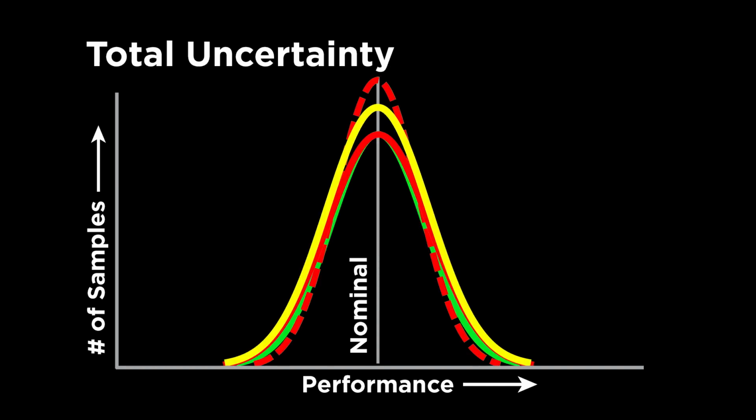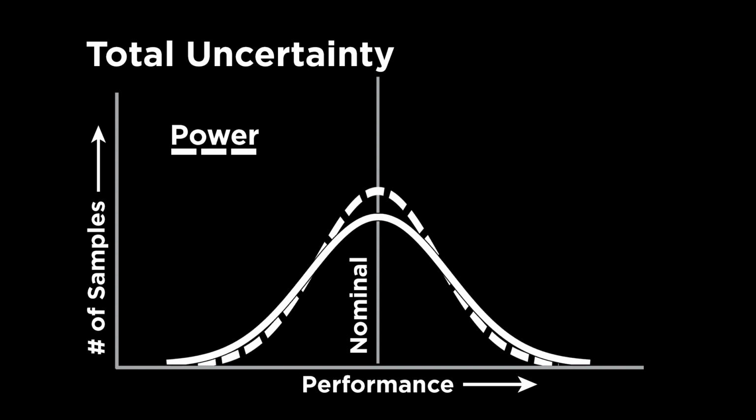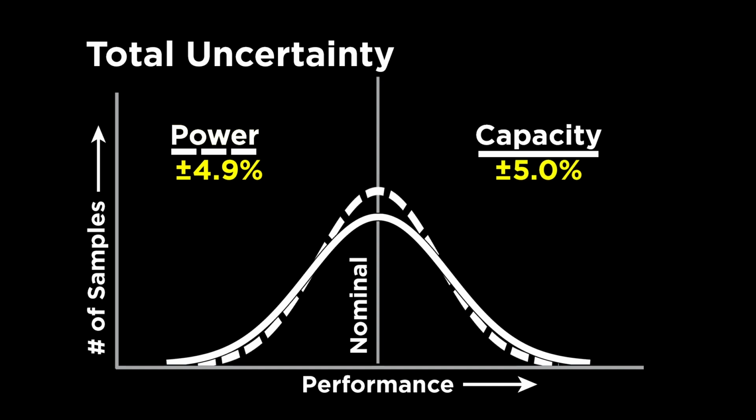When you consider the total potential impact of these 5 independent uncertainties, they can add up to a significant total uncertainty in a compressor's published ratings for power and capacity, up to 4.9% for power and 5% for capacity. What's worse, the impact of these uncertainties tends to grow at lower evaporating temperatures and higher pressures. Why are these uncertainties a major concern?